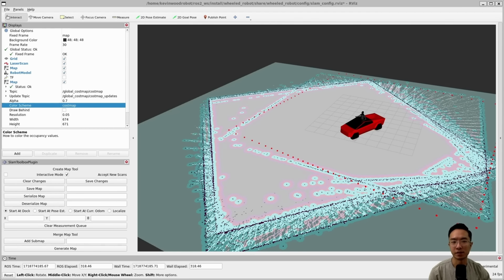The final step is to navigate your mobile robot using nav2. Now that we have set up everything, we have our map visible, we set up our cost map, and we also launched nav2 with the nav2 bringup. This will connect the command velocity to the actual robot. If you've done your remapping properly, which I've laid out on my website, then your robot should be connected. Otherwise, if the command velocity is not mapped properly, your robot will not move.